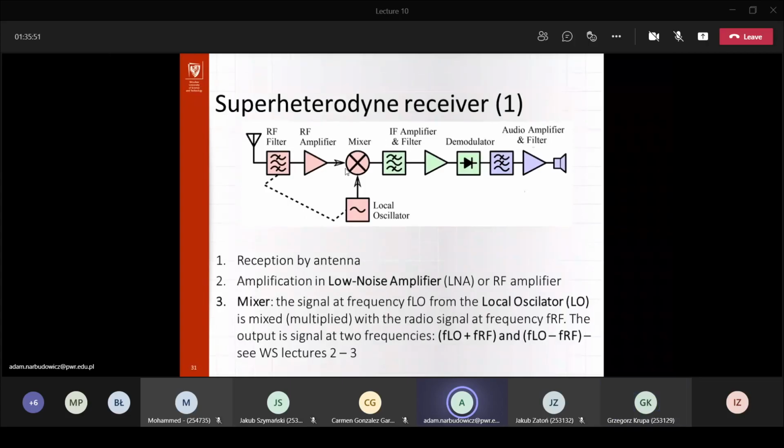For amplifiers, the general rule is you want it to stay an amplifier, so not to drive it anywhere close to the nonlinear range. Here comes the 1 decibel compression point. For many devices, the so-called dynamic range is defined between the noise floor, the minimum noise, and the beginning of the nonlinear range.